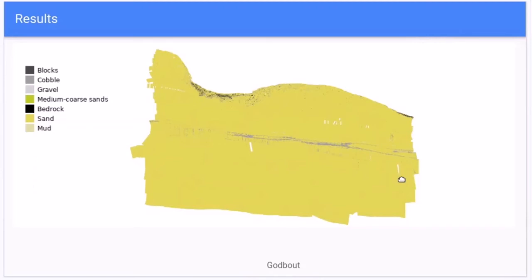So you can see that there are very weird and geometric lines here, and these are actually the overlap sections in between the two swaths, which create what appears to be a ridge where there isn't a ridge. So basically this appears like cobble, because there's some sort of an edge effect in the overlap between the two sections.